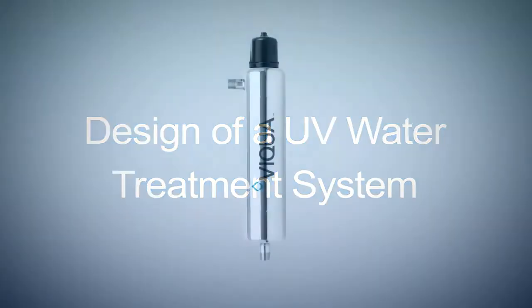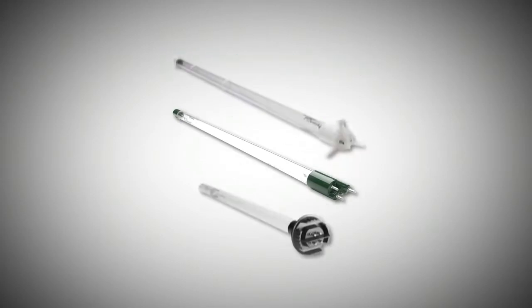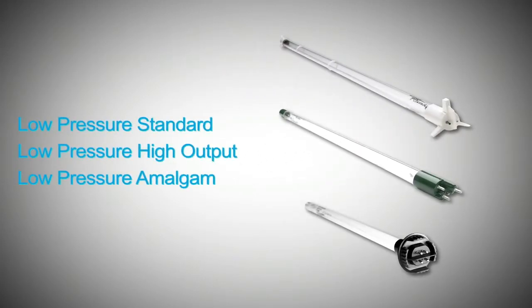Typically, there are 4 basic components to a UV system. The heart of the system is, of course, the UV lamp. These are available in different configurations, including low-pressure standard lamps, low-pressure high-output lamps, and low-pressure amalgam lamps, each suited to different flow rates, applications, and footprints.